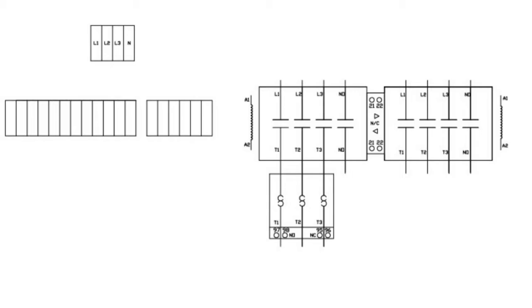We're not going to be using that at all right now. We're actually on a DC motor, so that's not shown on here, but I may add that if I get a chance to get you your DC power. But we're going to use the line 1 and neutral to get our single-phase AC power, because that is where we're going to feed our control circuit from.